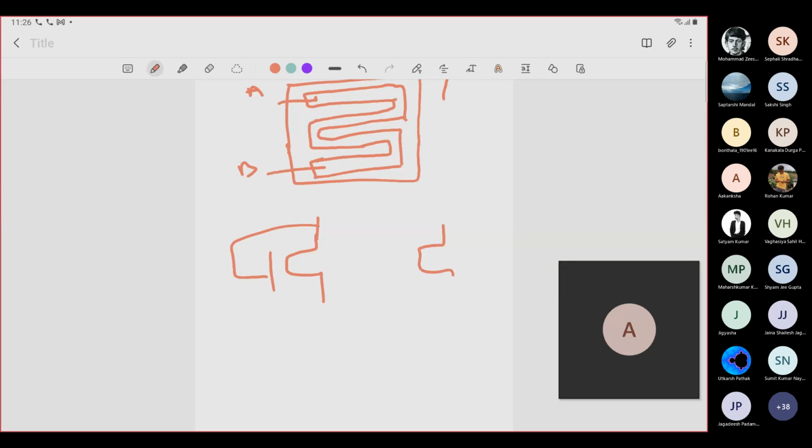In the MOSFET, there is a source, a drain and a gate. Here the source and gate are connected. Source and drain are interchangeable in a MOSFET device, so for convenience you can nominate whichever is the source or drain.